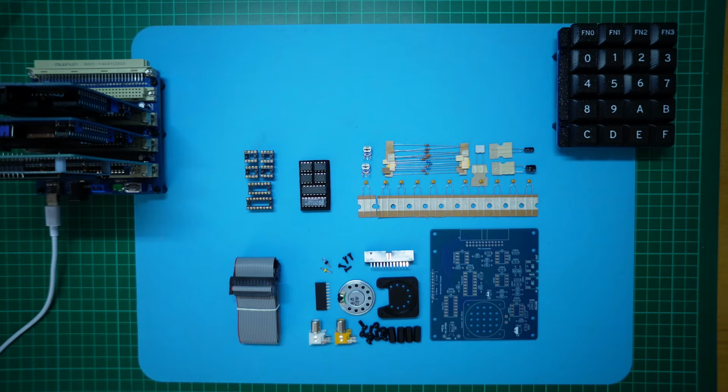This was very inspirational. One of the first inspirations was Mike's comment about potentially using a 4x5 matrix keypad to provide an additional row of 4 function keys. This would be instead of the original design's hardware debounced single function key. The ChipOS operating system, which the Dream 6800 implements, uses a single function key in combination with the 0 to 3 hex keys to implement 4 different functions, function 0 through function 3.